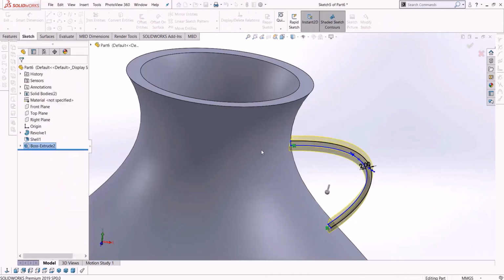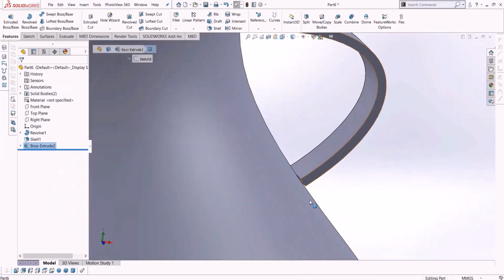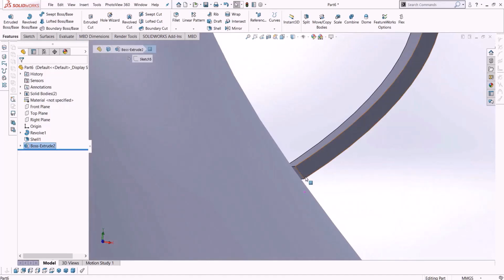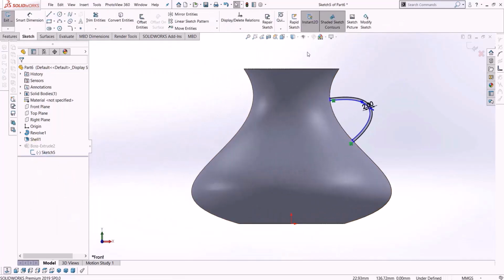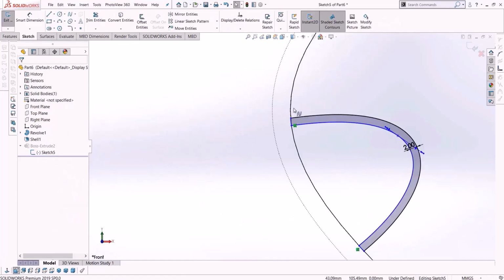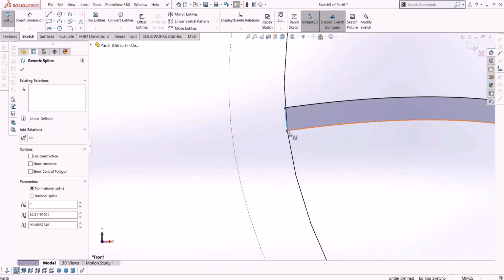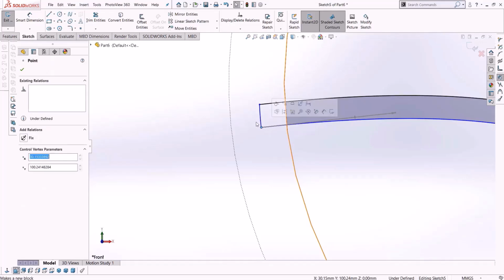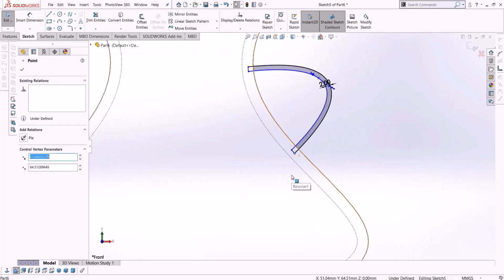Even if we increase the thickness, you will see that it becomes much more obvious that this method is not correct. Of course, if we just want to get it working, we have a trick for that, which is that when we see the thickness here, we can carefully remove this coincident option that is sticking this together, move this slightly a bit inside the meat of our vase, and also do the work for the bottom in this way, precisely.